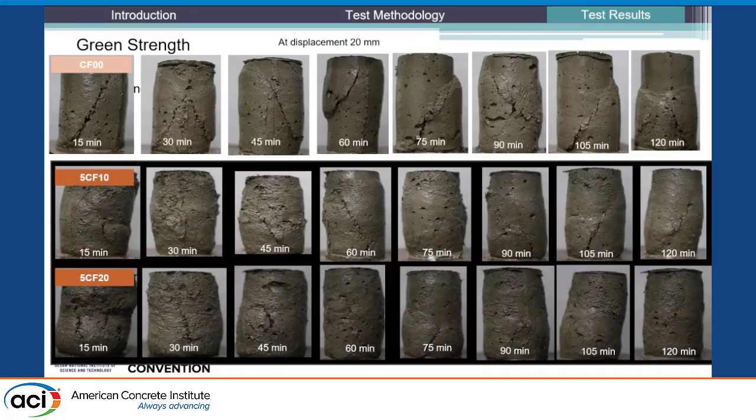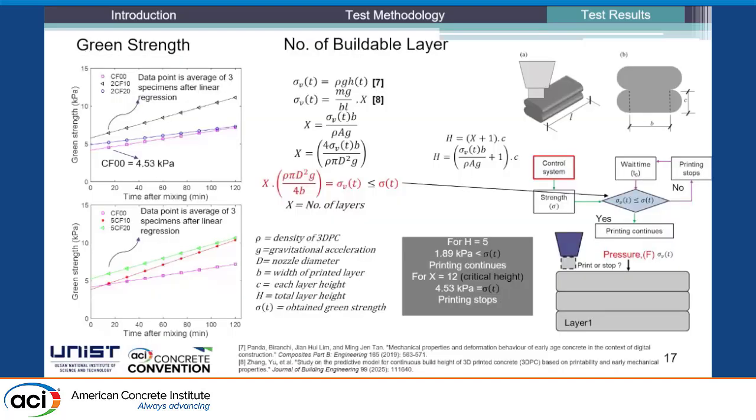And this is with the addition of 5 millimeter fiber. Here too we can see that the cracks, the CMF, had this kind of bridging property. If we compare the samples for all the curing times, this is the green strength we have.